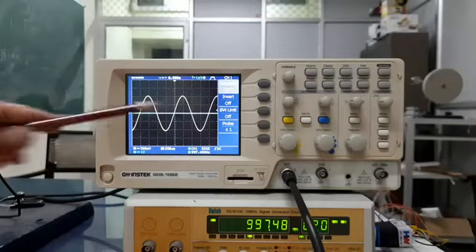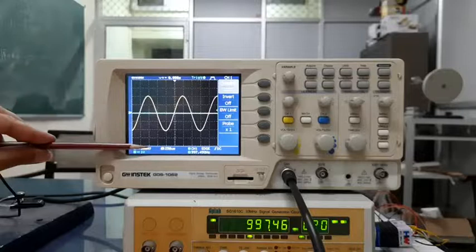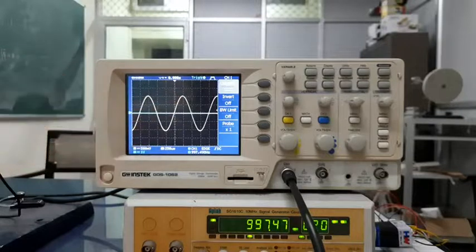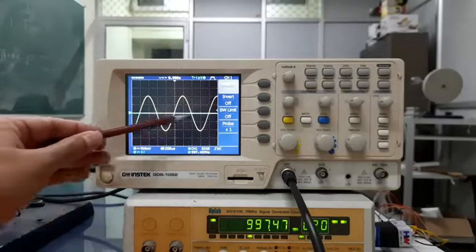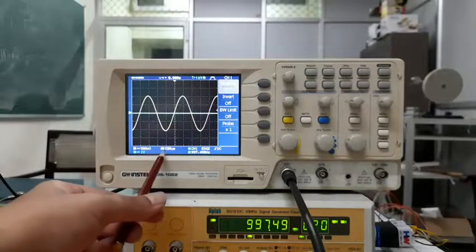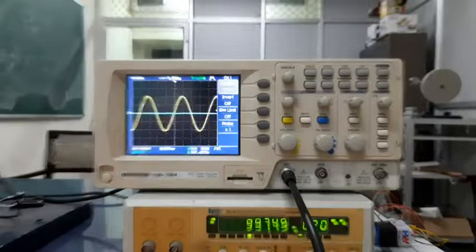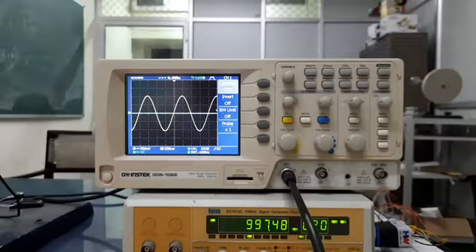What is its amplitude? So from 0, it goes 1 division, 2 divisions, and each division is 500 millivolts. So about 1 volt peak or 2 volts peak to peak. What is its frequency? So let's say it starts from 0 and one cycle is about 1, 2, 3, 4 divisions on the horizontal scale, which is 250 microseconds per division. So about 1 millisecond. So time period is 1 millisecond, frequency is 1 kilohertz. So this way we can make some rough measurements. In fact, this is the more common way of reading signals off the oscilloscope, but there is